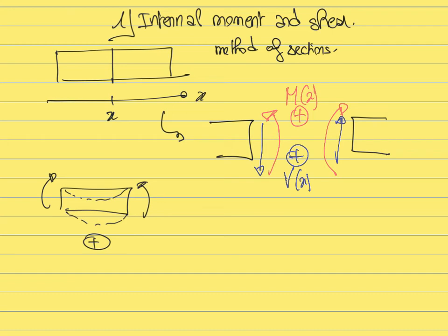So again, a positive internal shear will be a type of internal shear that is causing these types of deformation. Just as a note here, the positive sign convention for the internal shear is actually the opposite as compared to the sign convention for the shear stress. If you remember, for the shear stress, the sign convention is as follows.